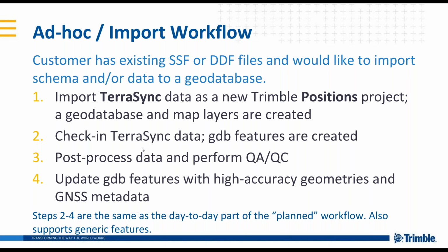Now, steps 2 to 4 here, check in, post-process, QA/QC, update features, those are part of the planned workflow. So that's why I said I wasn't going to show the second part of that workflow, because I'm going to demonstrate it here. And it also supports generic features. So this was an area of when we first released the TerraSync support within Trimble Positions, generic features weren't supported. Now they are through this workflow.